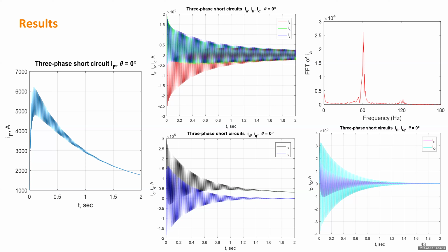And this is the damper winding currents. The damper winding currents will increase right after the fault. This one is a Fourier transform of the current. So you can tell the fundamental harmonic is still 60 Hertz, but because there is some fast dynamic, you also have some higher harmonics. I'm not going to analyze in detail why the waveform looks like such a plot.